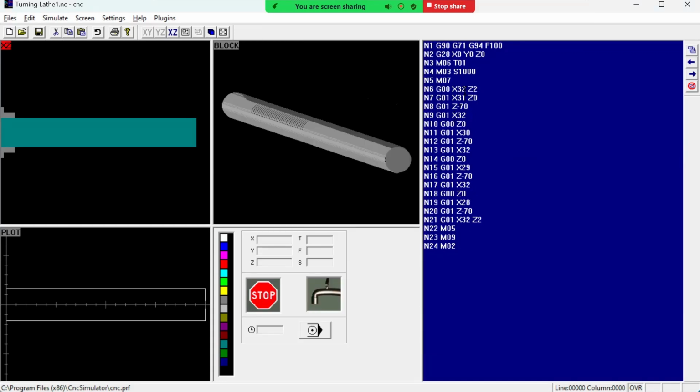Here, the only change we need to make is we have to divide all the x coordinate here by 2. We'll keep the z coordinate as it is because it is unaffected by the system of the coordinates. You just need to divide the x by 2. So x 16, this would be x 15.5. I'll quickly do this. So we have replaced all the x coordinate.